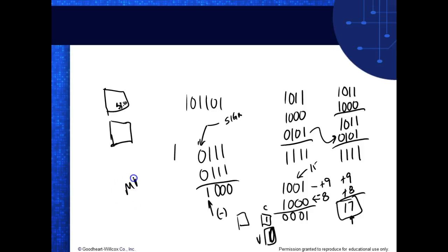All our math uses the same status register, and all our logic uses the same one, right? So what happens if I add and then don't check for a carry right after the add, and then I do a logic operation? Your status register is going to be set according to the last instruction that was executed when you checked. Y'all understand that? Yes or no?